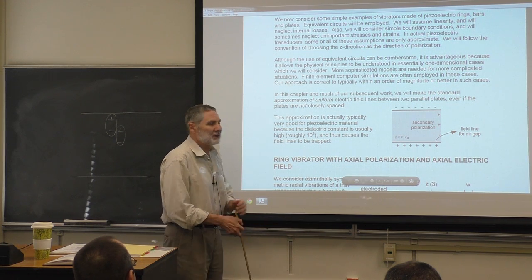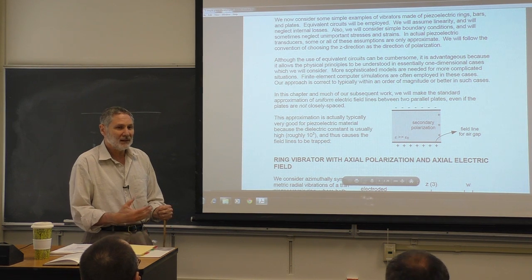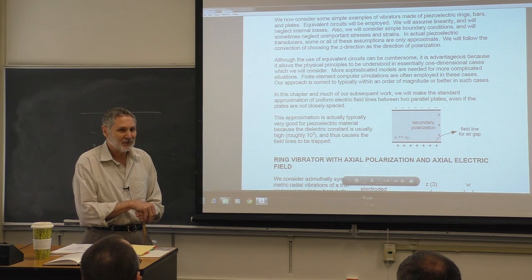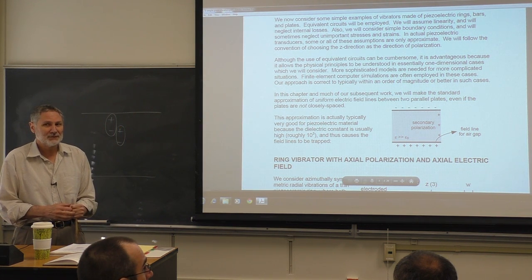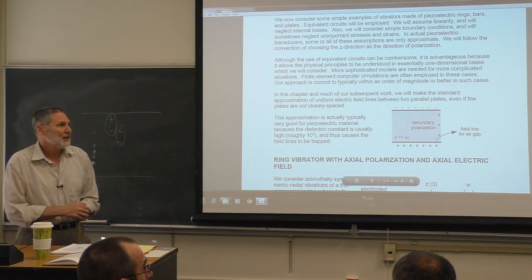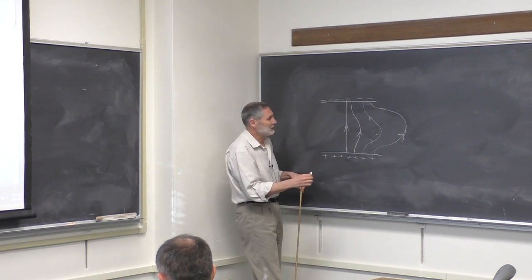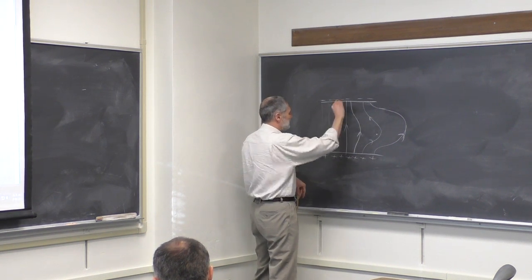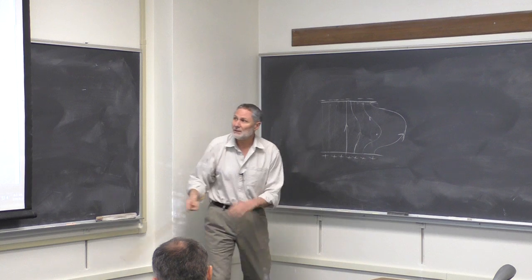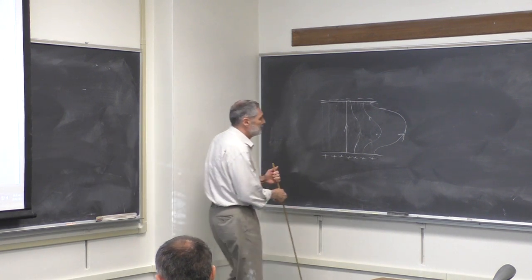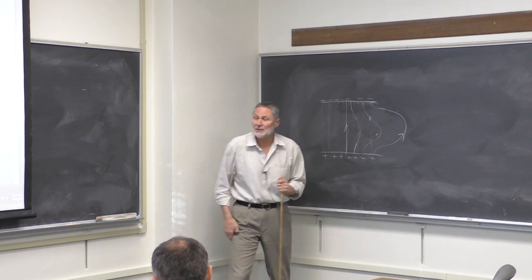Now what happens when you put the dielectric in there? What happens if we were dealing with a magnetic field and we had a highly permeable substance like iron and we put it in there? What happens to the field lines? This is a real practical thing: transformers. Do you guys know what happens? The lines get essentially trapped. It's the same with magnetism and electricity. If you put this material in here with a very high epsilon, permittivity, and you get all this polarization, the field lines will be trapped in here and approximately uniform.